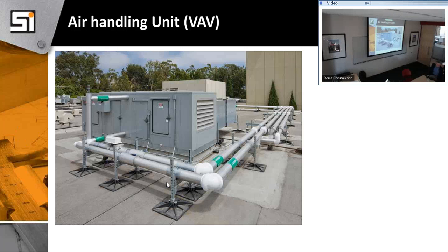On an existing build-out, basically, is it from your VAV that you're changing out, or is it all the way up to the package unit? I think they're not going to make me, that's another thing, the package units are a lot more efficient. They're requiring more efficient units too. But if I'm doing a retrofit, they're not saying pull that thing off the roof. But if I need different types of controlling that VAV box, and I'm changing stats, those are going to be code compliant stats. So if it's a multiple suite building, there's a chance that you touch one piece, how many pieces are going to be affected?